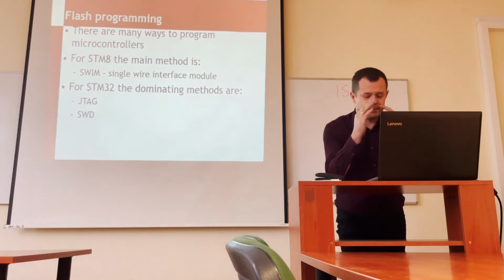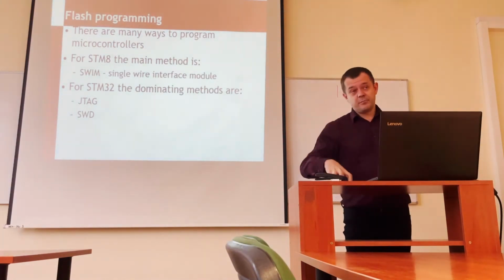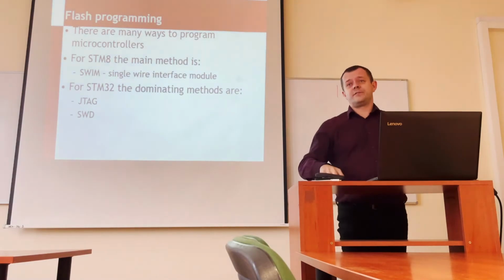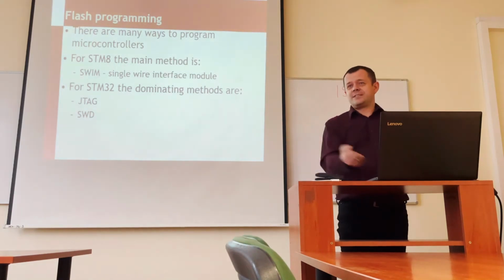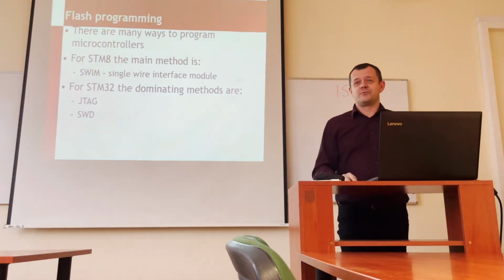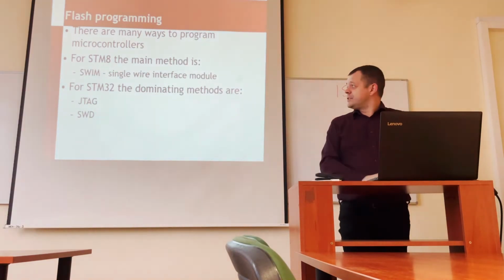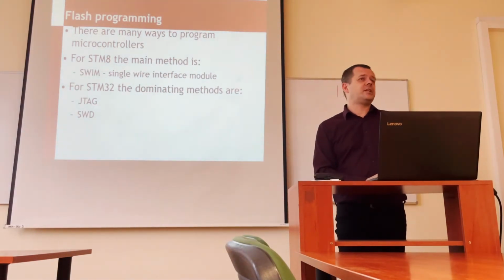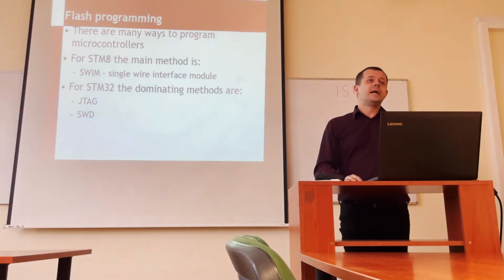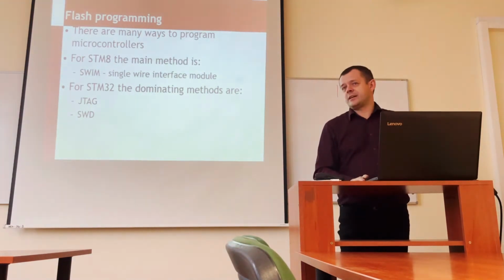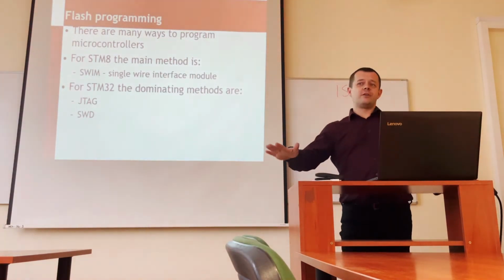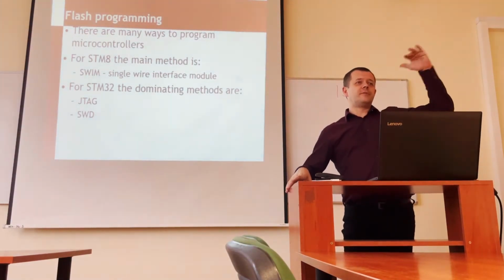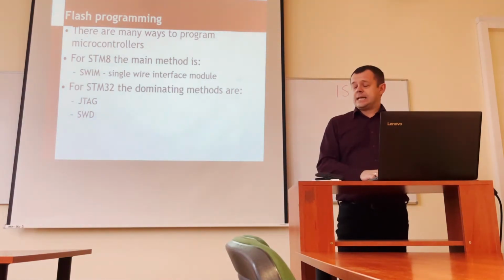I remember the times when programming, having a board with a UART interface just for programming, cost no zloty, no euro, because it was just connecting to a computer and running free software to program. But if you wanted debugging, JTAG was the only option, and the JTAG interface cost about 200-300 euros, plus dedicated software for the JTAG communication, which required an additional few hundred euros. So that was the difference: zero cost UART programming, or high cost JTAG debugging.